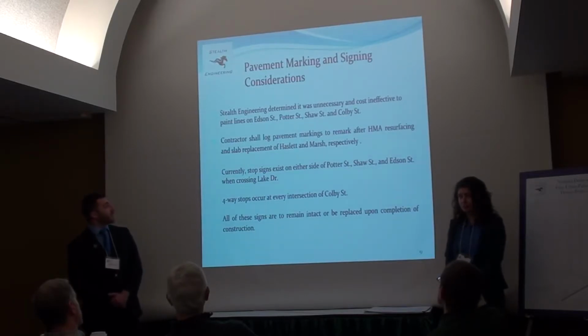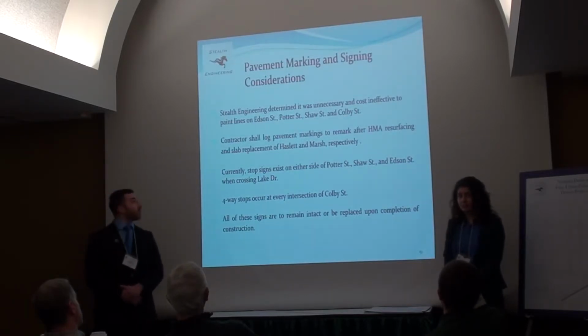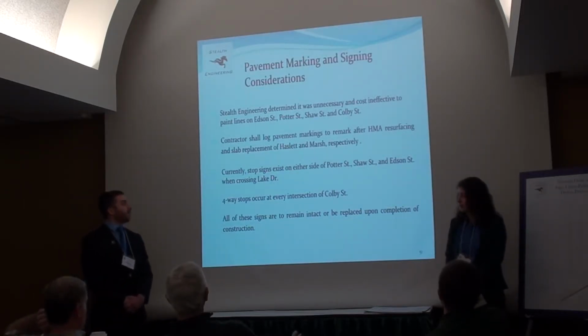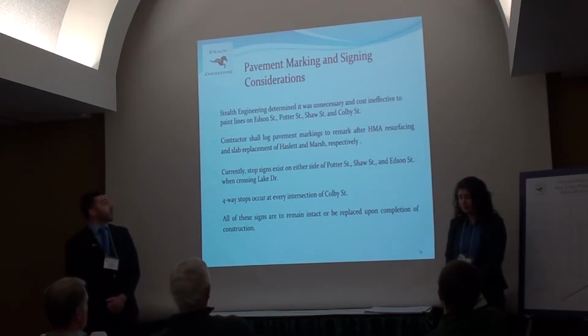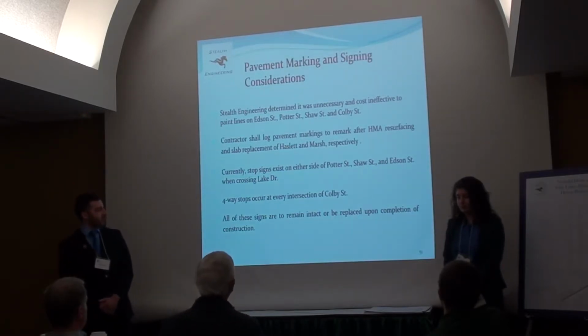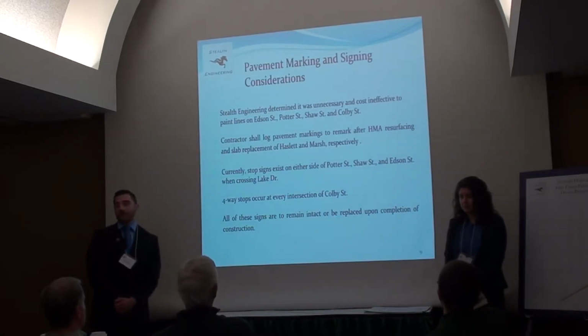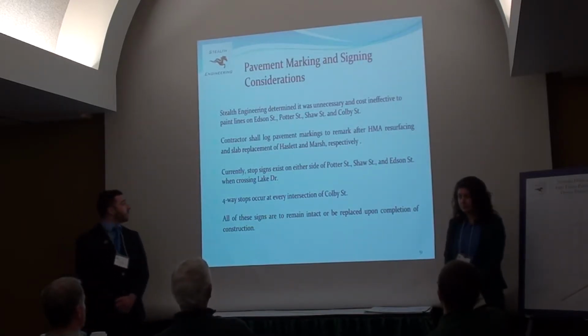Considerations for pavement marking and signing. Due to the low volumes of the link roads, it was deemed unnecessary and cost ineffective to paint any lines on Edson Street, Potter, Shaw, or Colby Street. With respect to construction operations on Hazlet and Marsh, the contractor shall log current pavement markings to be remarked after HMA resurfacing and slab replacement for Hazlet and Marsh respectively.